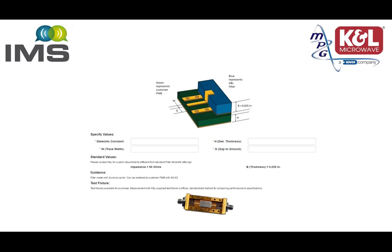In this page, you are required to enter the dielectric constant of your PC board, the trace width, the dielectric thickness, the gap to the ground, etc. In addition, we are also offering the filter in a test fixture that is solely built on your PC board information as shown below.